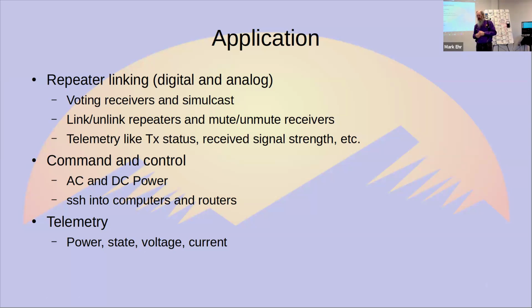And of course, there's all kinds of things built into the protocol for retransmit and all of that kind of stuff to deal with collisions and just flutter and noise and whatever. The key thing, though, of course, if you're in the 5 gigahertz band and the 60 gigahertz band, even more so, is it's got to be line of sight.